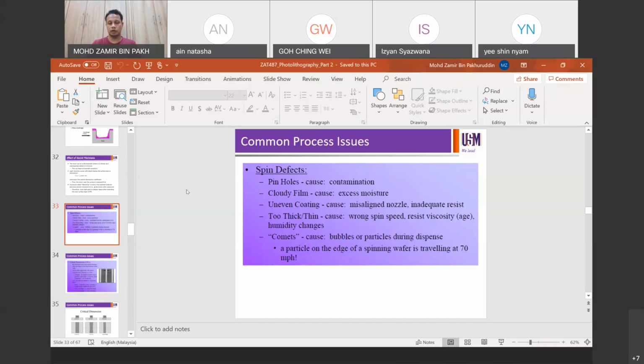If you look at the 8 steps of the lithography process, the defects could be from the priming process, the coating, the hot plate or cool plate process, exposure, alignment, PEB, development, hard bake, and even the robot arm itself. So the defects can be from any process in lithography.